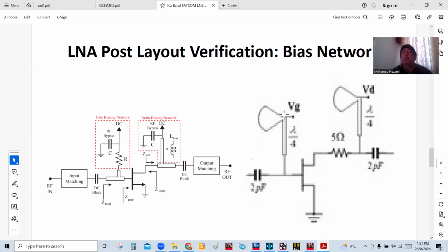So therefore, the effectiveness of this here is really the same as this cap, except it operates over a wider band. So if this is short in here, and this line is a quarter wavelength, then looking this way vertically at this point, the impedance is high. It looks open to the RF signal. And all of the energy, of course, will go into the device. Likewise, on the drain side, same thing. We want all of the power to go into the load, and none of it will go into the radial stub.